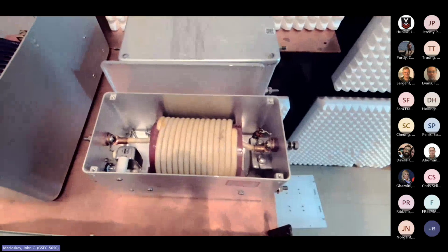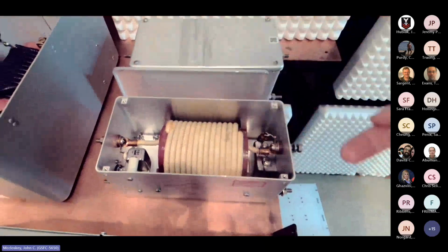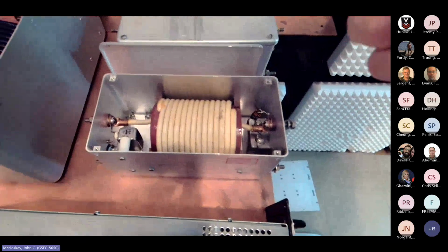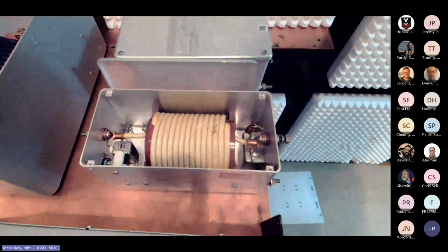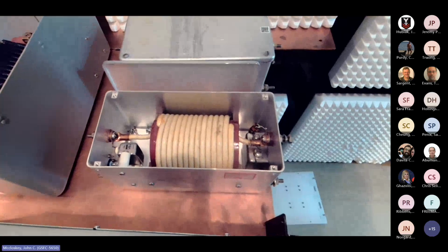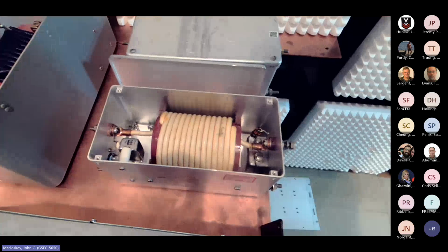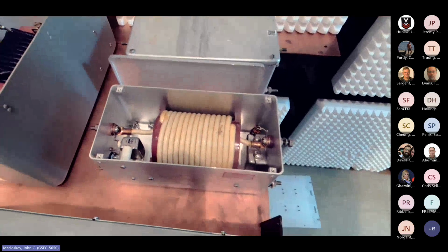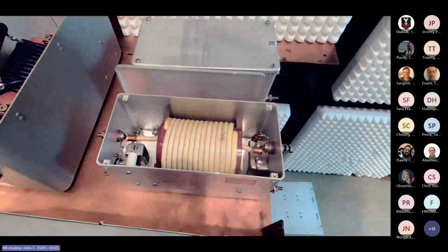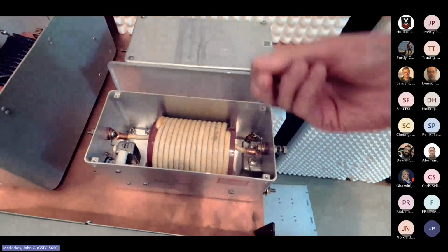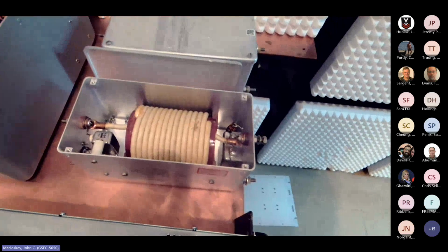We generally run a dedicated return wire, with the ground plane as your intentional current return path. We generally run a dedicated return wire with our send wire twisted with it. That configuration has a much lower inductance per unit length, on the order of maybe 100 nanohenries per meter. So even if you run that configuration for 50 meters, you're getting toward 5 microhenries total.